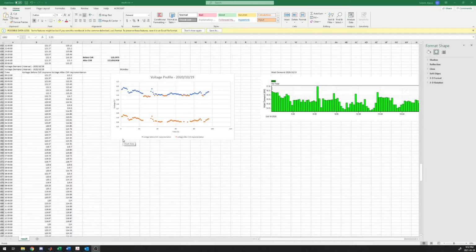Overall, this summarizes that CVR is an efficient method for reducing power consumption, especially if the voltage to a bus is trending above nominal voltage, in our case 120 volts. There is an important limitation to this method, which is choosing suitable loads for implementation, such as constant resistance loads, and it should not be used on loads such as motors or HVACs, because if the voltage to these high power loads were reduced, they'd just be pulling more current, so the energy savings would not be there.